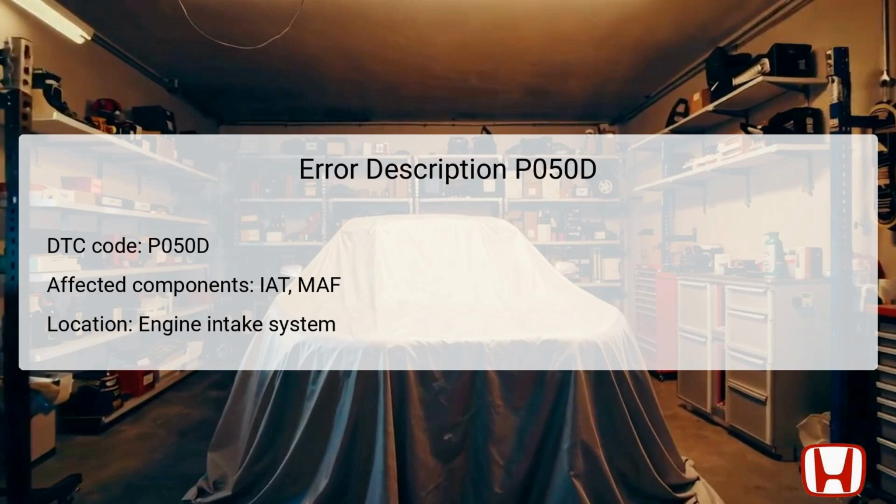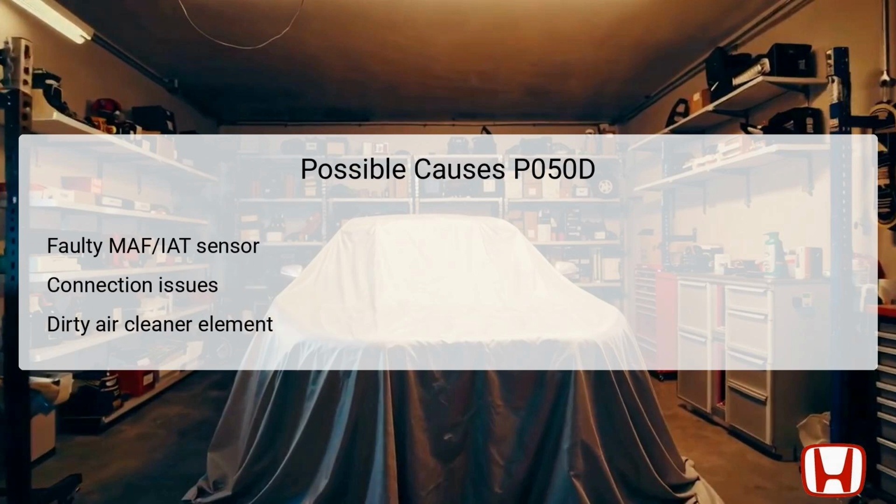These components must be verified to determine if they are operating within their specified ranges, directly impacting the vehicle's performance during initial starts. The possible causes for a P050D error code can vary widely, often encompassing several sensor malfunctions or connection issues. A faulty MAF or IAT sensor can provide erroneous readings, leading to improper air-fuel mixture specifically during cold starts. It's crucial to inspect both sensors closely.